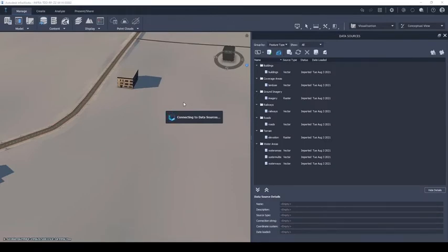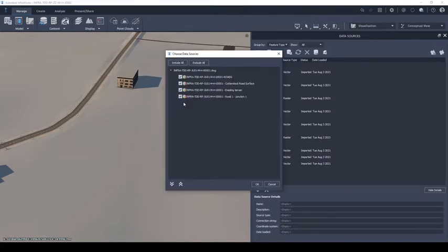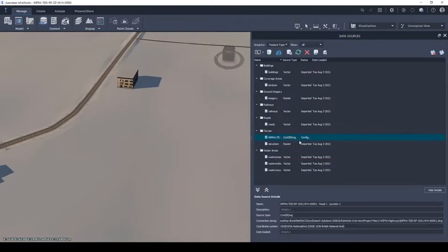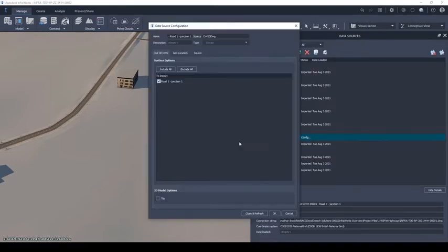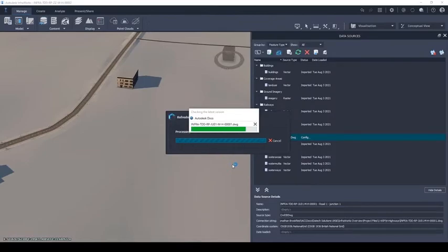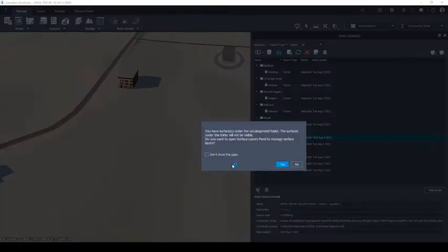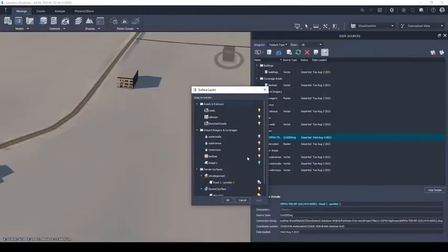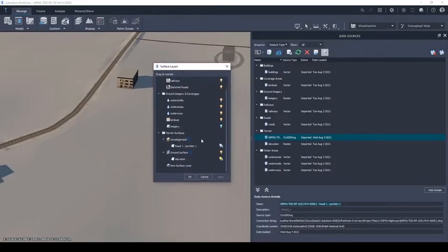Civil 3D surfaces are imported by connecting a relevant DWG to Infraworks via the Data Sources panel and then selecting the pertinent surface or surfaces they'd like to import from the list provided. When importing a Civil 3D surface, users need to categorize the terrain surface as a ground surface, place it above the existing elevation in the hierarchy, and ensure it has been toggled on for Infraworks to display the data.